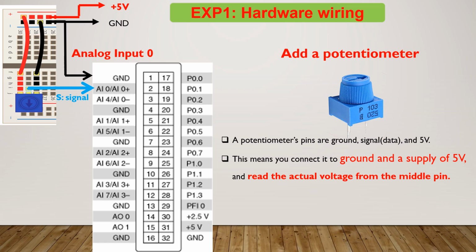It is very simple to read an analog signal from the physical environment to data acquisition, and how we can read an analog signal from the potentiometer by the data acquisition card USB-6009. It's very simple to understand and very simple wiring. We have two wires, a black wire and a light blue wire. The black wire is ground and the light blue wire is AI0, the signal from the potentiometer, connected to terminal 2 to read this type of signal.